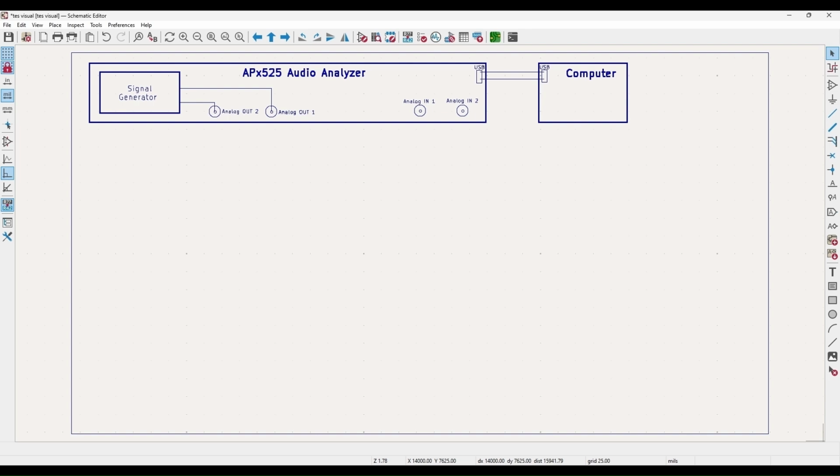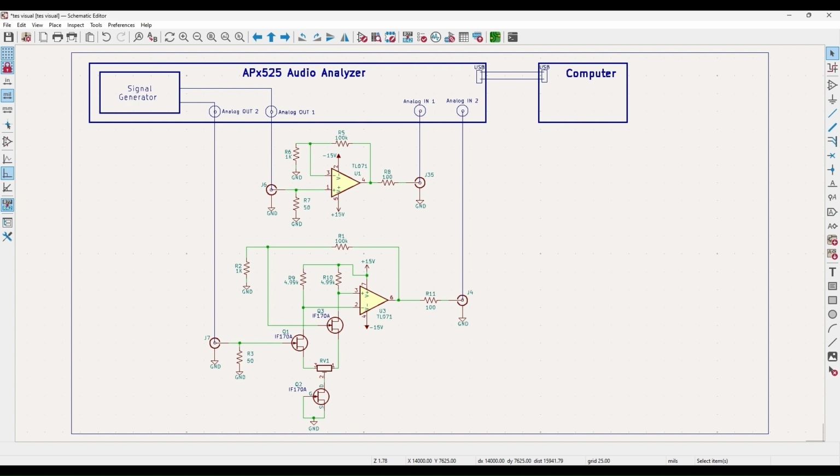The output of channel 1 will be connected to an op-amp module with a TL071 wired as a non-inverting amplifier with a gain of 100 that is contained in a shielded enclosure and connected via BNC cables. We will compare this to another module that has the same op-amp but with a JFET differential amplifier added to the front. 3 JFETs are used.